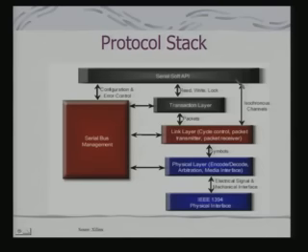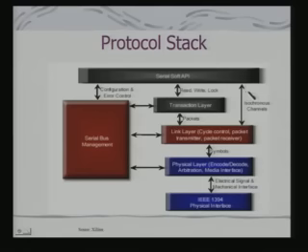And when it is an isochronous flow, we had already discussed isochronous flow, that is media data delivery, they are not strictly read write transactions. So, under that circumstance, you really need the transaction layer to come into play. There would be direct transfer, and that transfer is managed by the link layer, and all these things through a serial bus management system.